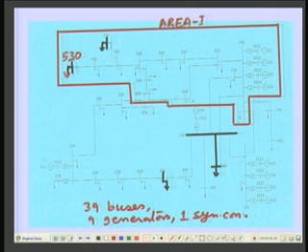And then a load flow is conducted to find out what is the voltage at this point. That is, you perform repeated load flow for different loading conditions in this area to plot a VP curve corresponding to the bus number 530.